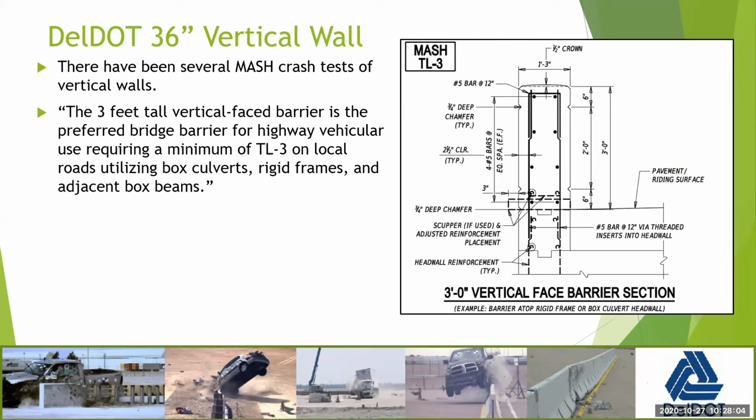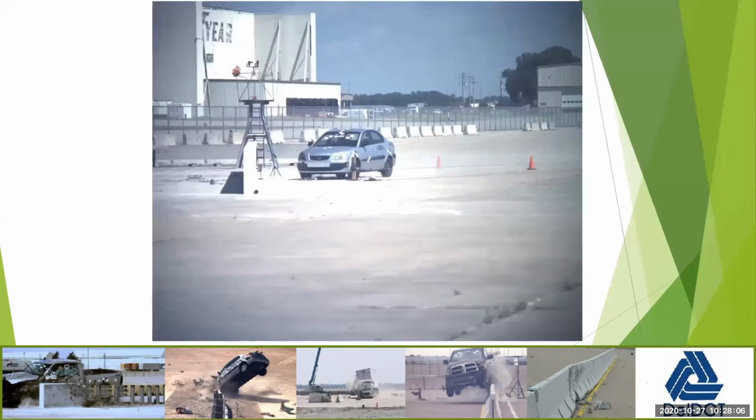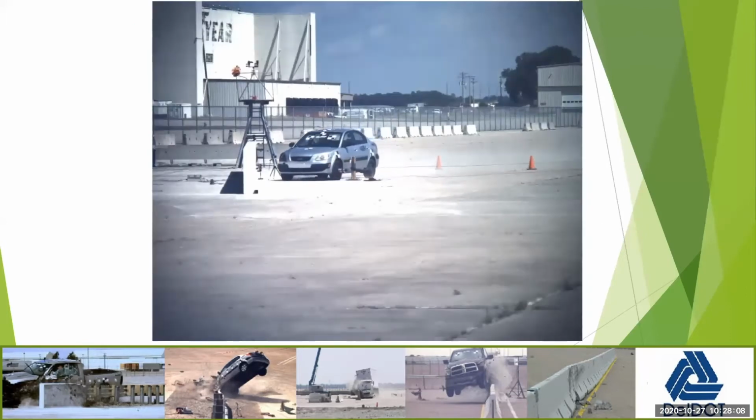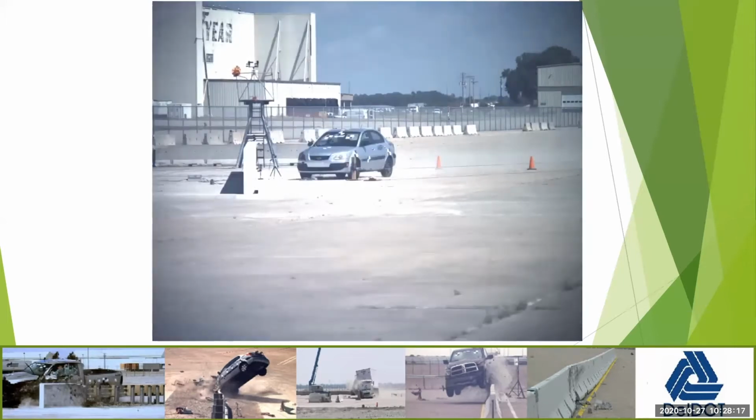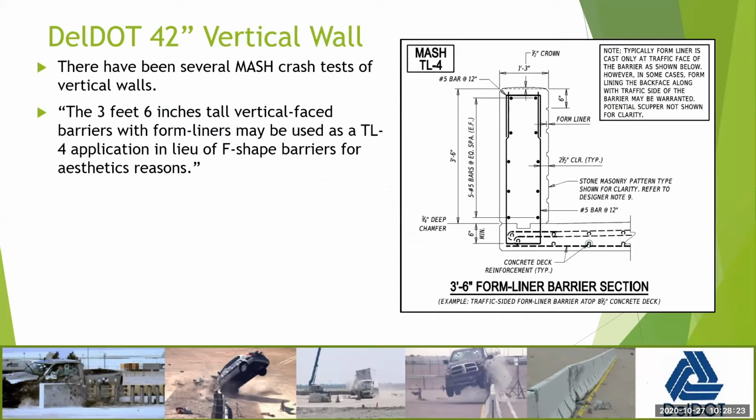36-inch vertical wall. Really not much has changed. I'm not going to spend too much time on this. Let me get you back to your spec training. Here's the crash test for it. And just look how little uplift is on the car when it crashes into that vertical wall. Compare that back to the safety shape, the single slope, and also the curb in front of that vertical wall.